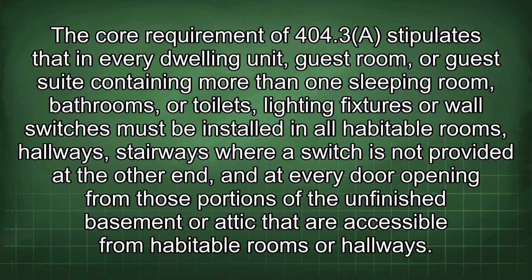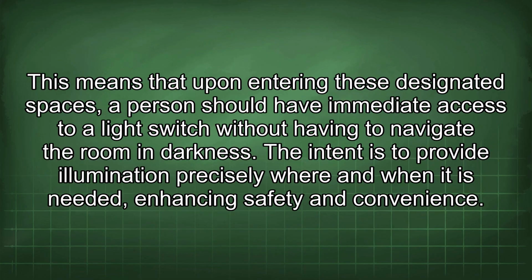The core requirement of 404.3 stipulates that in every dwelling unit, guest room, or guest suite containing more than one sleeping room, bathrooms, or toilets, lighting fixtures or wall switches must be installed in all habitable rooms, hallways, stairways where a switch is not provided at the other end, and at every door opening from those portions of the unfinished basement or attic that are accessible from habitable rooms or hallways. This means that upon entering these designated spaces, a person should have immediate access to a light switch without having to navigate the room in darkness. The intent is to provide illumination precisely where and when it is needed, enhancing safety and convenience.